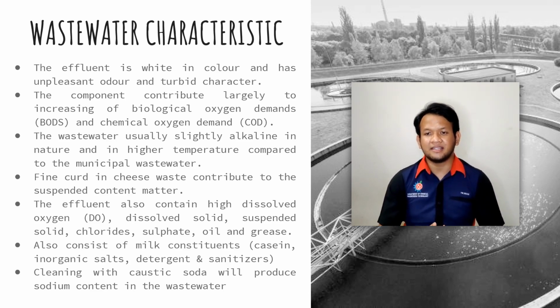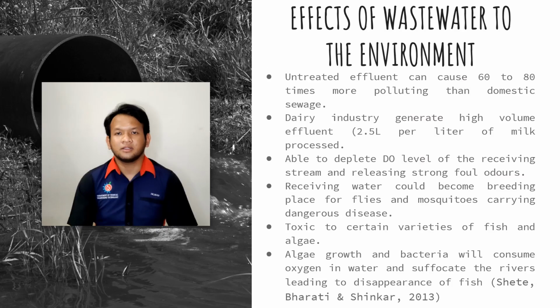The wastewater is usually slightly alkaline in nature and at a high temperature compared to municipal wastewater. Fine cut-in waste contributes to the suspended matter of the wastewater. The effluent also contains high dissolved oxygen (DO), dissolved solids, suspended solids, chlorides, sulfide, oil and grease, that will be treated along the treatment process. This wastewater also consists of mixed constituents such as casein, inorganic salts, detergents and sanitizers. And lastly, the cleaning process with caustic soda will produce sodium content in the wastewater.